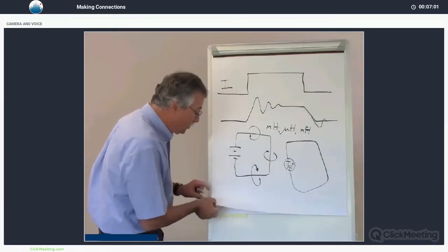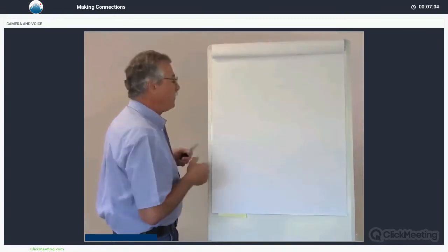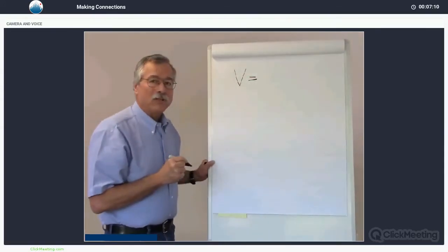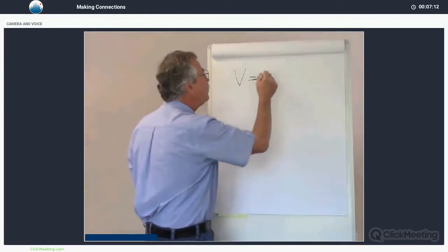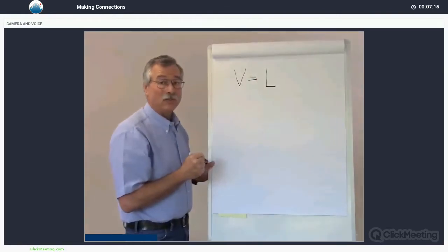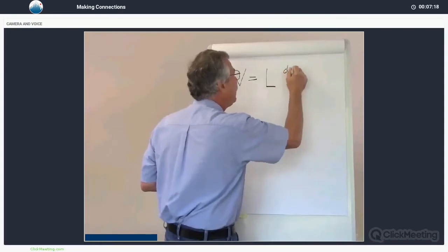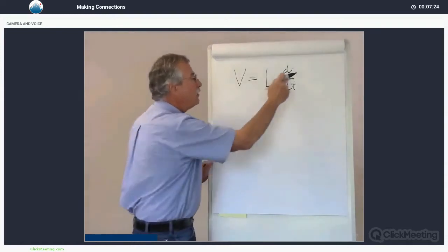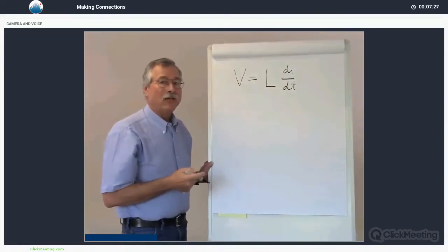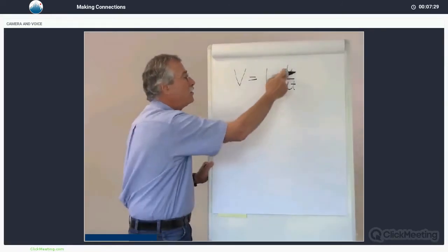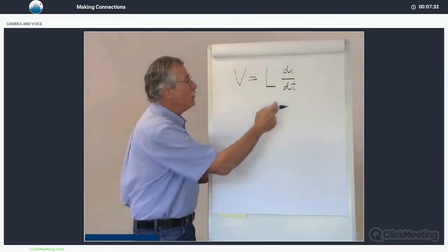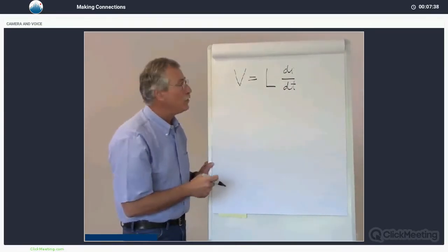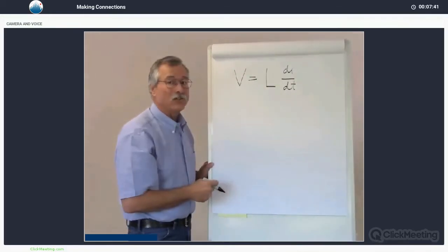There is a formula, and it's the only one we're going to throw at you today, that is extremely important. The amount of voltage that we induce in a circuit is equal to the amount of inductance, L for Lenz, and the speed of the change of the current. In our laser driving business, we may run into dozens or hundreds of amps, so dI is a number in that area. The amount of time it takes to go from 0 to hundreds of amps could end up being nanoseconds, a very small number, so this combination is going to be a very large number.